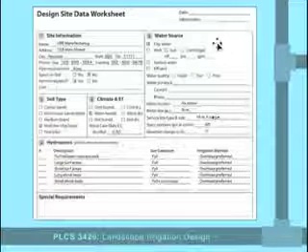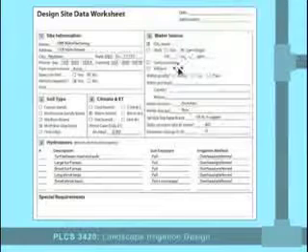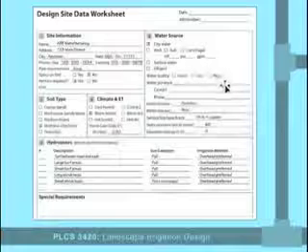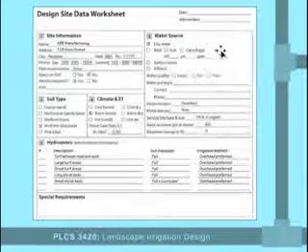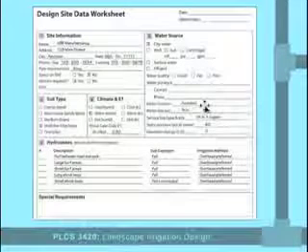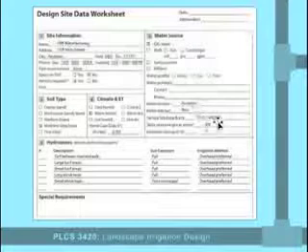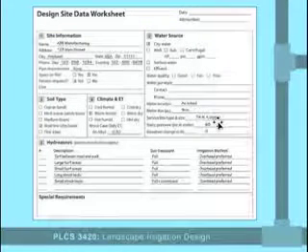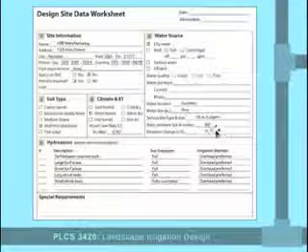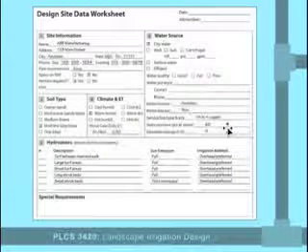In the case of this example, it's city water, so information about the well and pumps and so on is not required. Water quality information is also not required because city water is going to meet a certain minimum standard. Then there's the meter location as noted on the plan, meter size, and the type and size of service line coming onto the property. And static water pressure measured at the meter here is noted as 65 psi, or pounds per square inch. We'll get a lot more into that as we go on.